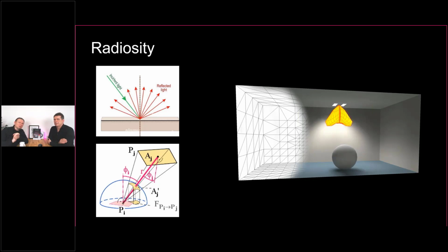The direct part is easy and is always the same, but the indirect part depends on how many indirect patches you create and how much light comes from one surface to another. You can calculate it infinitely, and you can see it here in this wireframe sketch. We have some automatic size division of the surfaces. You can see it in the larger triangles and the smaller triangles, where we hit a lot of energy on a surface. Then automatically the indirect patches will be smaller.